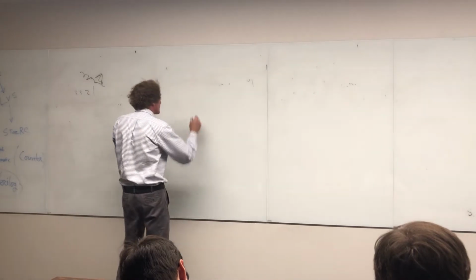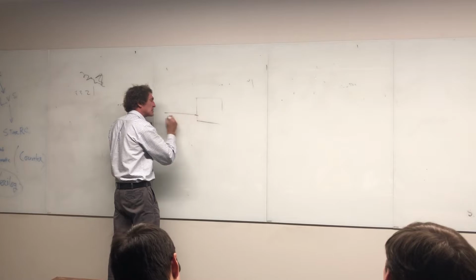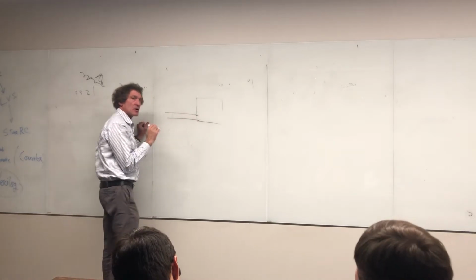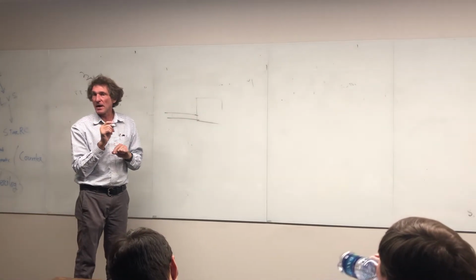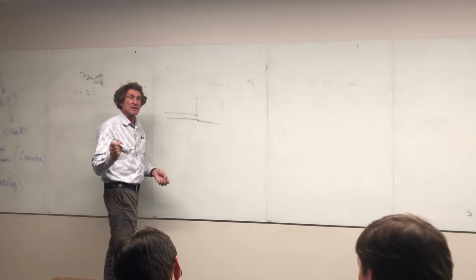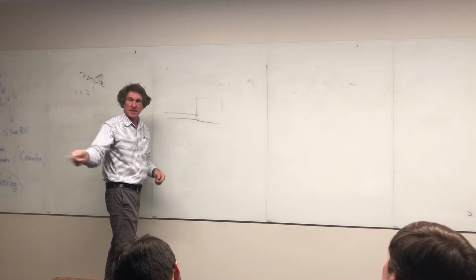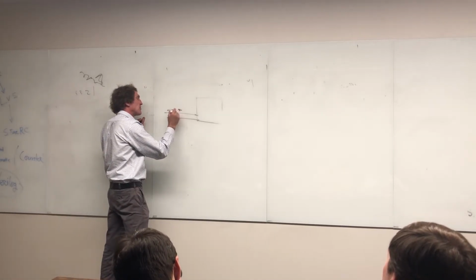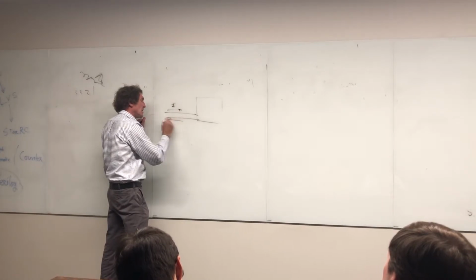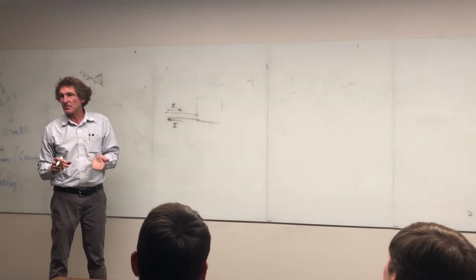If you have a device over here and you've got a power supply with a power cord, I'm not going to draw the ground connection, and I'm not going to talk about when you've got plus or minus 120. This is the simplest possible thing, like the power supply that you stick into the wall that drives your laptops and tablets. The current's here in the differential mode. There'll be a current here, the exact same magnitude, opposite directional current in the other lead, right?